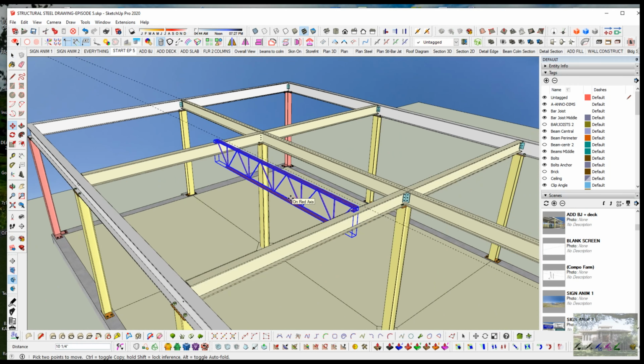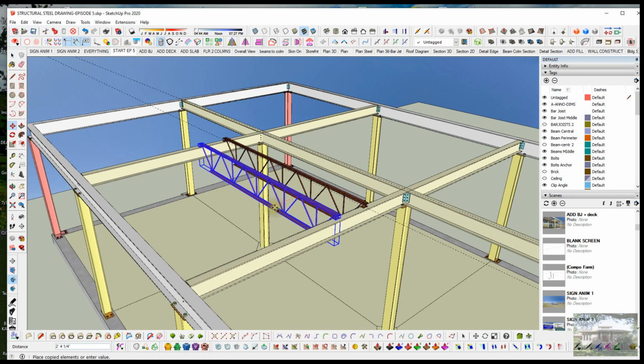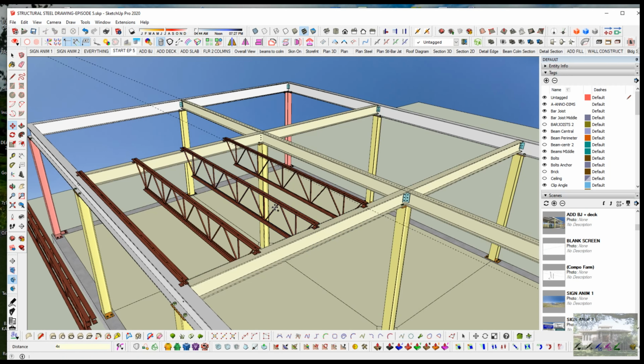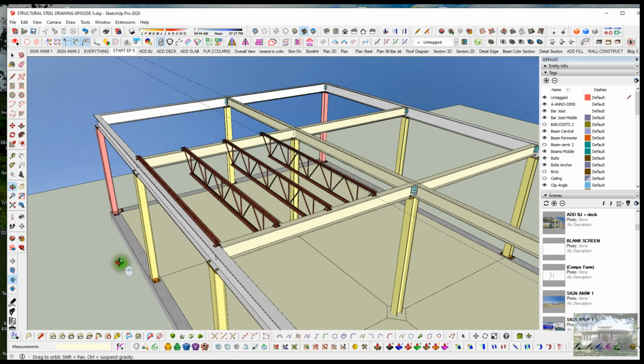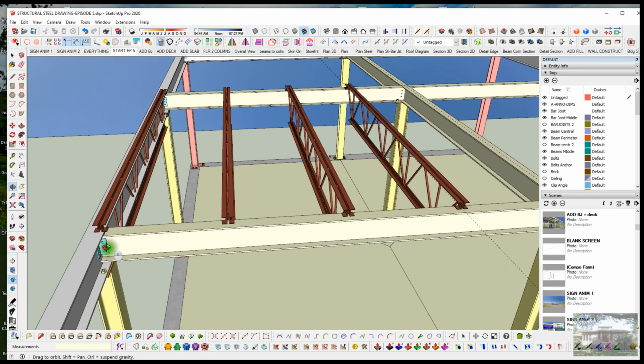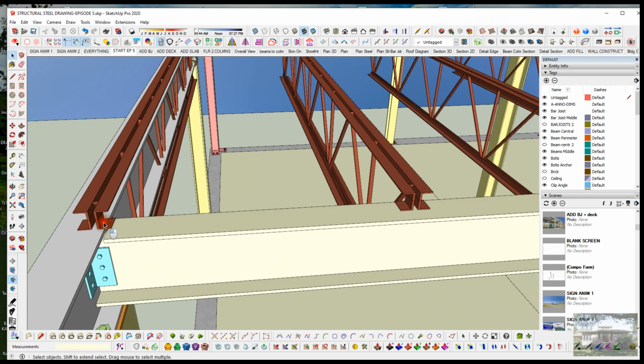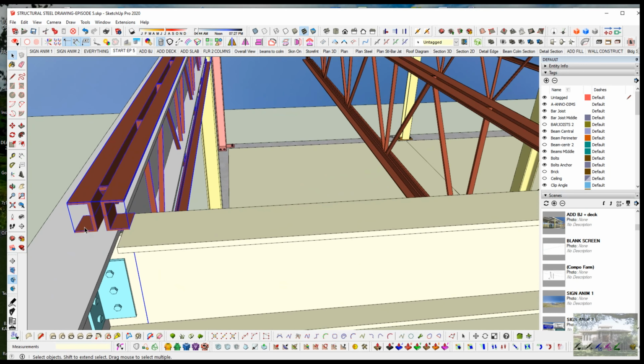So move Control to copy. And I type in 48 for 48 inches. And we'll go 4x. Looks like we got more than we need. 3x. That didn't quite do what I wanted to do. It should have backed off down to 3 again, but I don't know what I did. But SketchUp will take any bit of input that you put in there and give you another chance if you haven't done something else first, which I probably did according to what happened there.